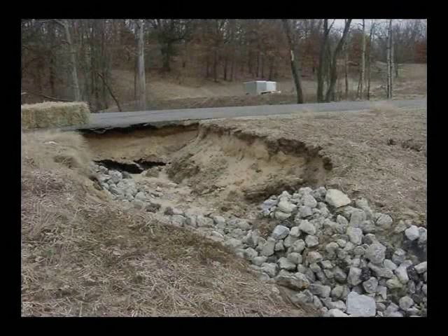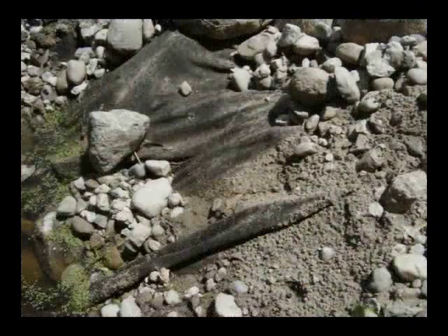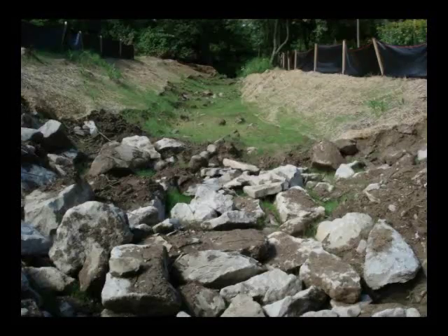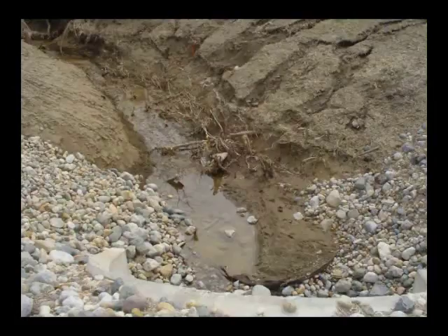Riprap is an erosion control measure. One of the most important things to remember is that no matter what purpose riprap is used for, proper rock size and thickness must be based on the maximum expected water velocity or wave energy. In most situations, filter fabric should be placed between the riprap and the soil. Rock that is too large may allow sediment transport between the rocks or may allow runoff to pass through at erosive velocities. If rock is too small, the energy of moving water may move the rock and destroy the structure.